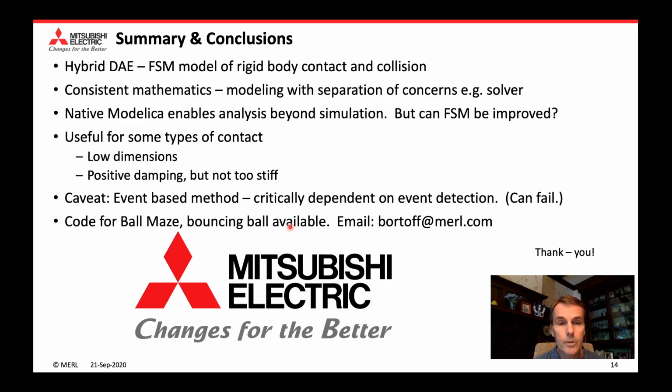I think this is probably useful for very limited types of problems, so low dimension with a little bit of damping. One caveat: this is critically dependent on event detection, and I've seen failures in the standard tools that we use for Modelica, because this is an event-based method. And so this can fail if the event detection actually fails.